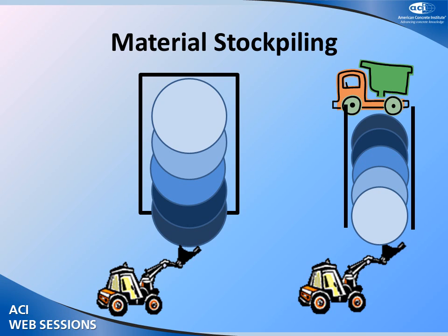The only trouble is I very rarely find a batch plant that has enough room to be able to do this type of arrangement right here. And so most people go back to this type of arrangement because of the space-saving ability, but they tend to ignore the fact that just because this is more convenient, they still have this same problem. They're getting one load of sand that's wet, then another load that's dry, and then another load that's wet, and maybe even sand from different sources, which is going to play havoc with your calibration of your sands and your moisture meter.